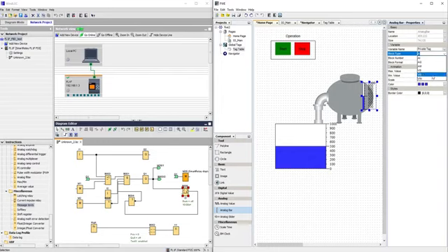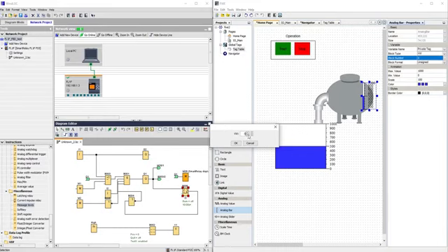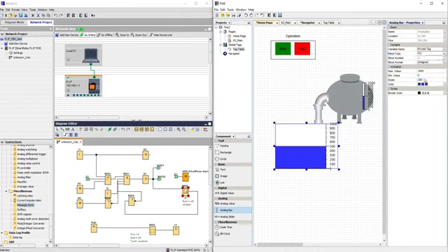So for that I have to go to VW and 0, yeah, that's 2, which is remaining timer. Here I need to mention it as VW 0, that is current timer, right? To check the operation of the queue here, whether the motor is running or not.